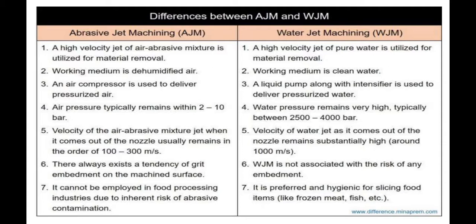Then in abrasive jet machining, air pressure typically remains within 2 to 10 bar. But in case of water jet machining, water pressure remains very high, typically between 2500 to 4000 bar. Next point about abrasive jet machining is that the velocity of the air abrasive mixture jet when it comes out of the nozzle usually remains in the order of 100 to 300 meters per second.